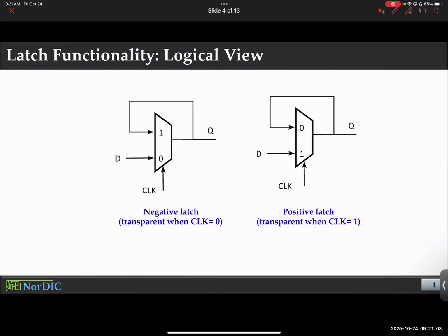Notice, I just want to highlight the similarity between what you have learned so far and the subtle change that made the circuit so different. Okay, so notice, a multiplexer uses a select signal. If the select is 0, the first input goes to the output. If the select is 1, the second input goes to the output. You all know this, right?